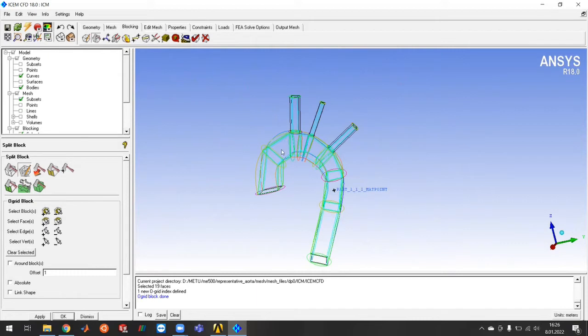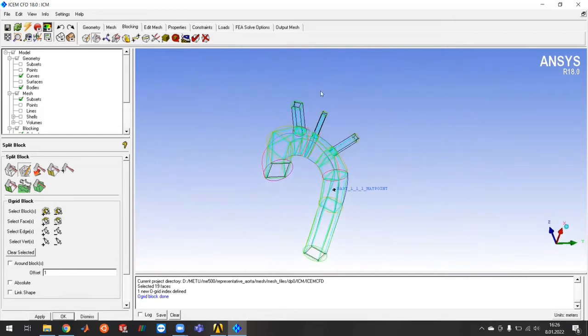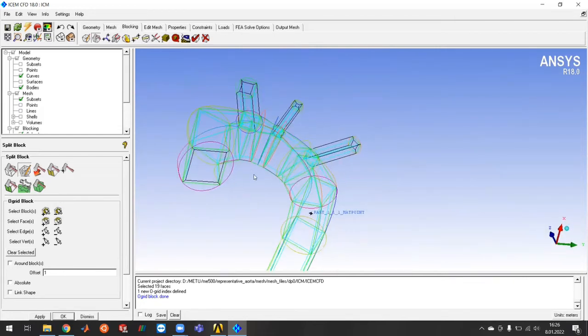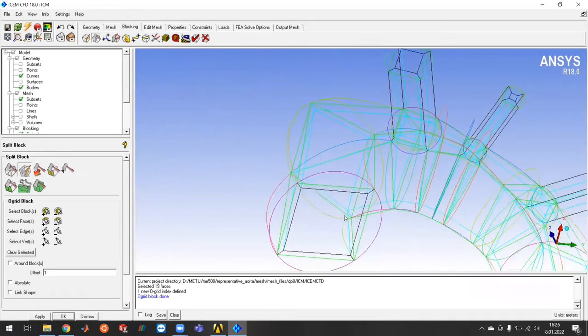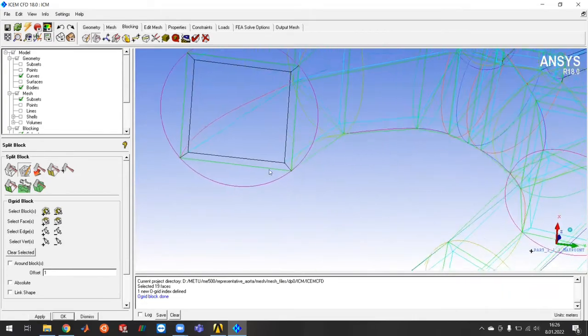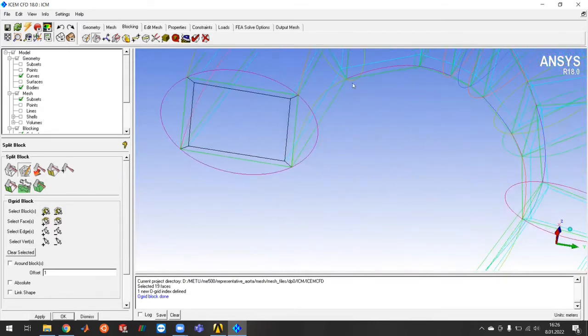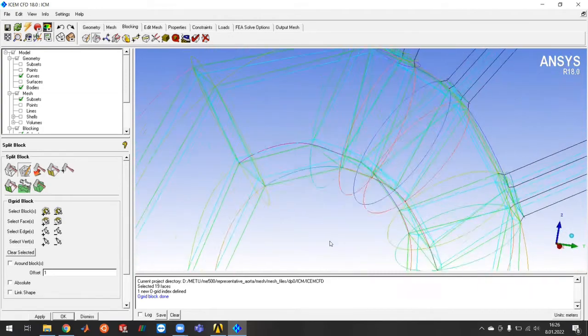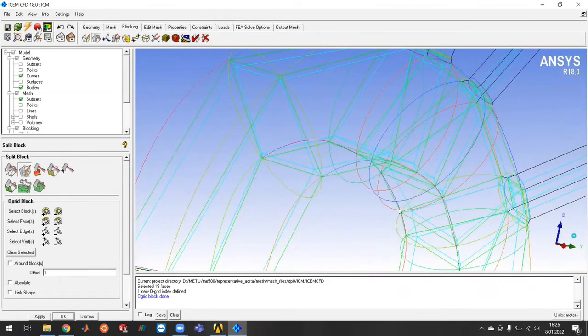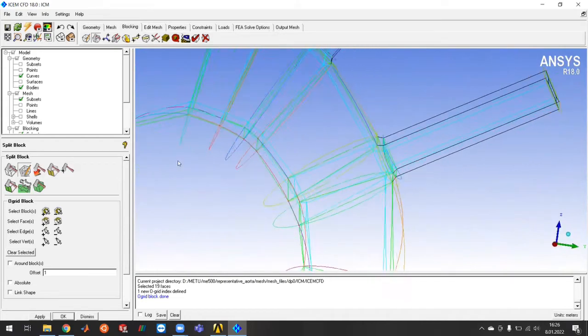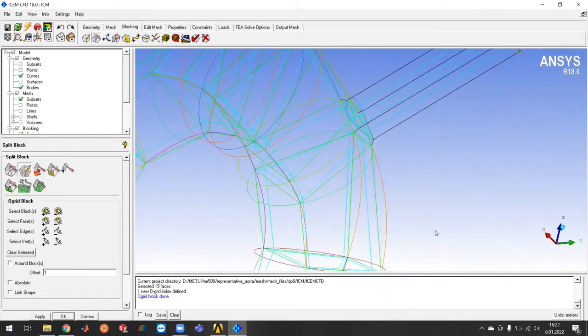As I said, the faces I selected are the faces that I'm expecting the flow to be normal to, the perpendicular faces to the surface. So let's see what the O-grid block has done. It divided all the blocks into 5 segments to create boundary mesh. See, it's a nice O-grid. It will allow me to use boundary mesh.